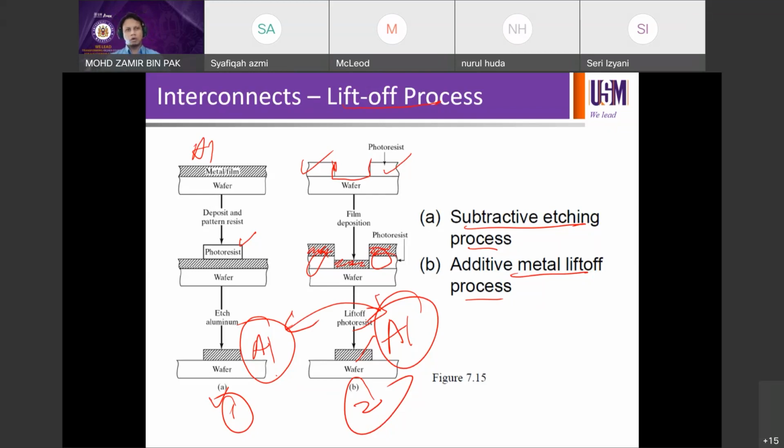It's always a combination of something, like what we discussed during the case study of lithography, right? You can either do RIE isotropic to scale down the polysilicon gate, and then RIE anisotropic and stuff like that, and eventually plasma etching of the resist in order to remove the resist and leave your polysilicon with smaller size on your device. Or you can work with whatever lithography that you have, but do multi-patterning, right? We discussed that. You can approach multi-patterning, but you have to do the process twice, right?